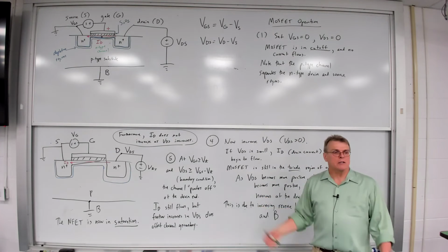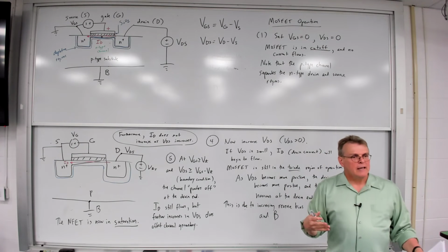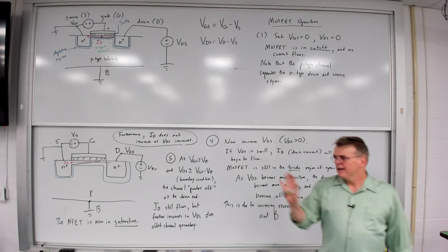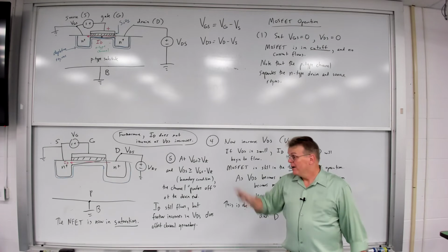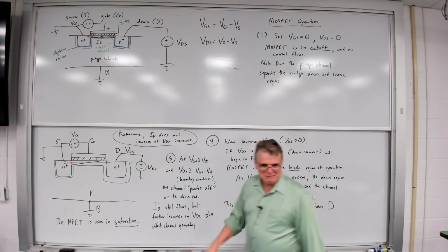Okay. So yeah, you could. You can actually increase the voltage on any semiconductor device to the point where you'll punch through and create a current path that doesn't really belong there due to breakdown. But in this case, unlike a Zener diode, we never want breakdown to occur in a MOSFET. That is not a good thing.